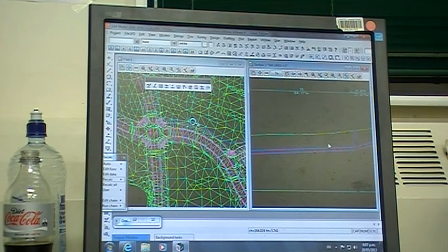You've got to make sure, as I said, that you've got some kind of fat built into it. We design to an AEP, an annual exceedance probability, but you hear people talk about it all the time on the news: the third time this year that we've had a 1 in 50 year storm. It's just a statistical thing. There's nothing stopping us getting bigger and bigger events. In Waitakere, we only designed to a 5-year storm. Quite often it goes beyond that. So I like to have a bit of fat up my sleeve rather than designing right to the very line.